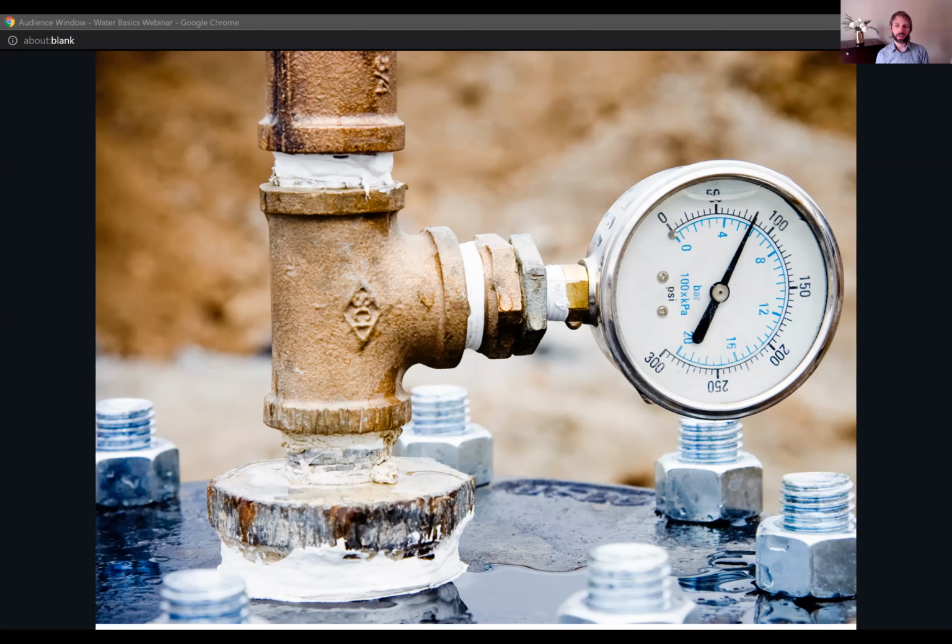Under 50 PSI, of course, you've got low water pressure, so it's not going to be comfortable or enjoyable. There could be leaks because of low water pressure, and it's just going to be annoying. Not something we're looking at from the green side, other than maybe detecting leaks. Over 60 PSI, you're going to have bad water pressure, and especially over 80 PSI, which is going to increase the flow rates of all those devices we just discussed earlier, and waste water and waste energy.